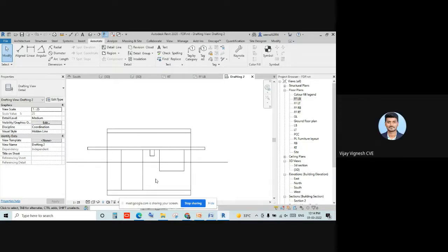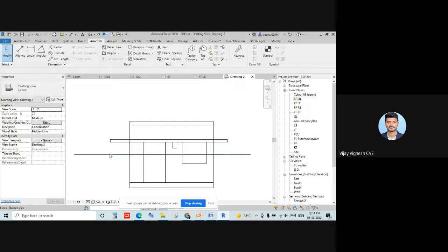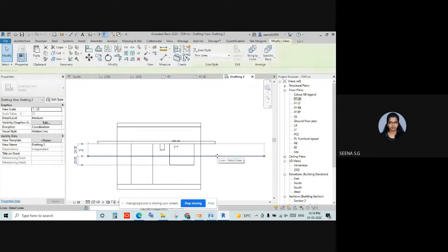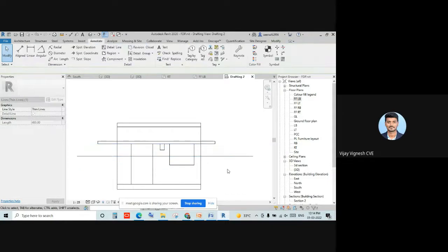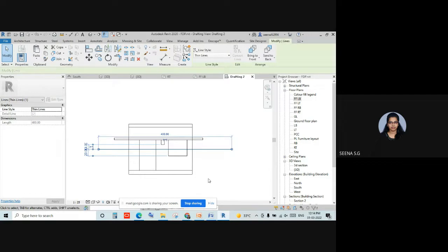In the beginning, it was showing the previous wall, that is the cut plane. Yes, this is called the cut plane. Revit automatically cuts all the views. So in our project, this is why it is showing that wall. By default, it cuts the wall at a fixed distance. So the cut plane cuts our building, and that's why we can see the floor plans.